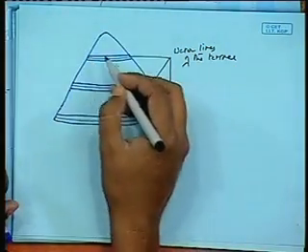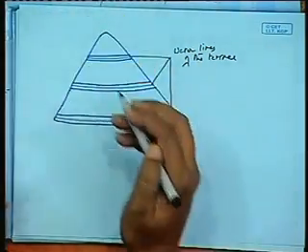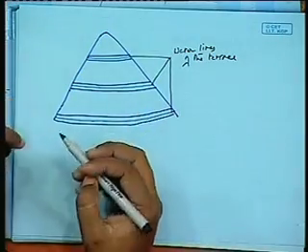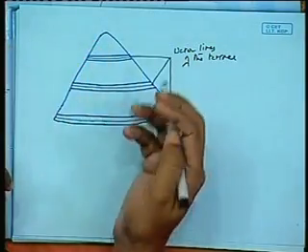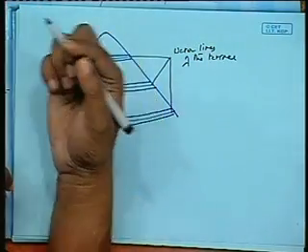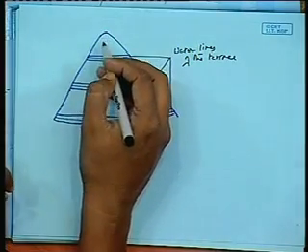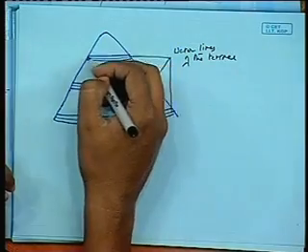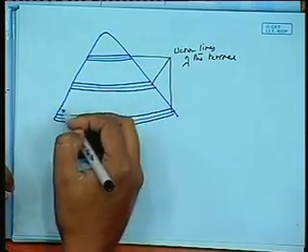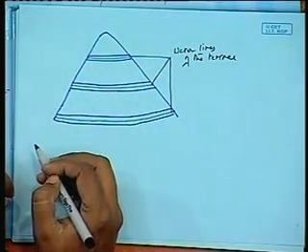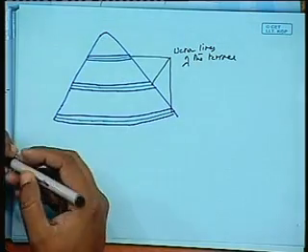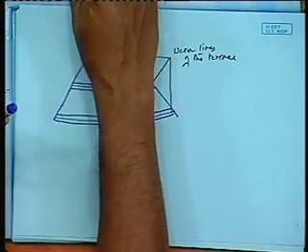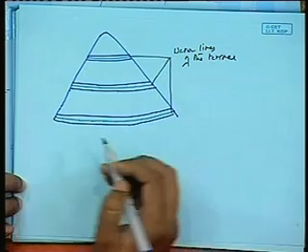So, as you can see, this would be encircling, as in a mountain road or a road near a slope, as the slopes keep rounding off. Similarly, all these slopes would be combining together, and the water which is supposed to come out through the slope would be diverted to the terraces, and through the terraces it would come down at the bottom. Okay. This is a particular kind of terrace, the broad based terrace that I have discussed.